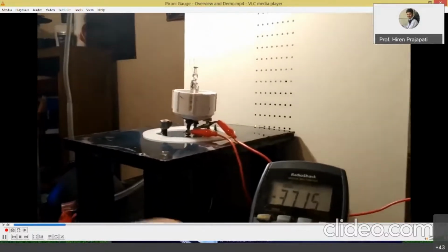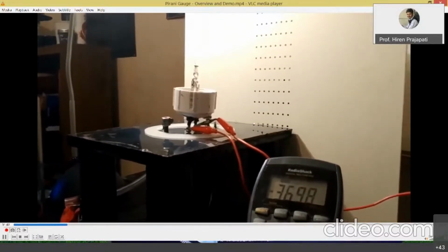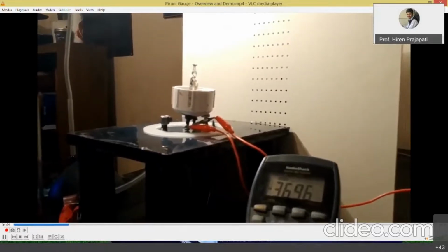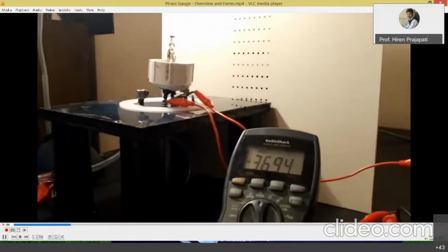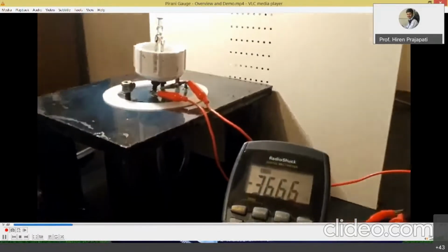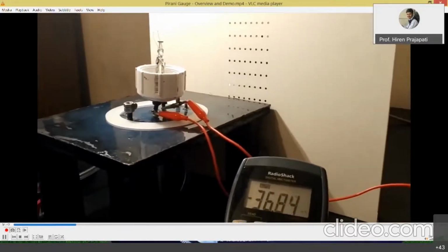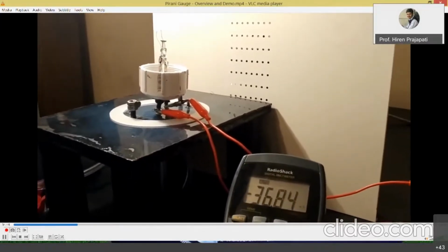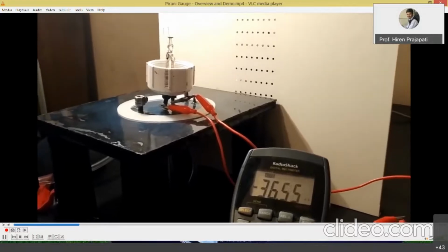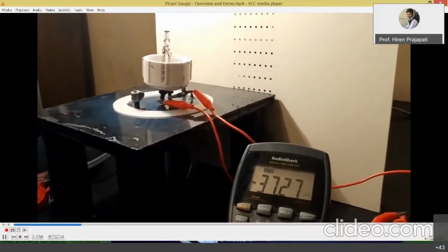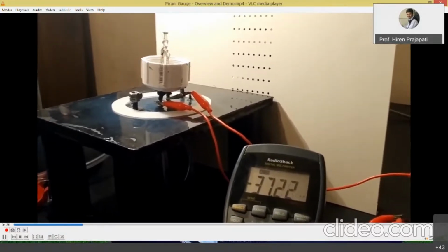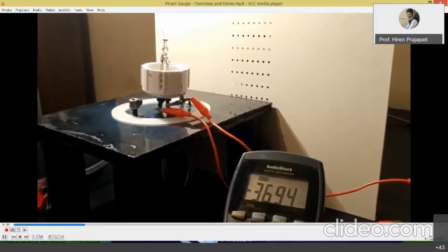And what that means is that basically this is an indirect measure of the temperature of the filament, and because it's being heated by the very small electrical current that we're supplying, the temperature will depend on the pressure of the gas surrounding it, because obviously the gas is going to be absorbing heat from it.